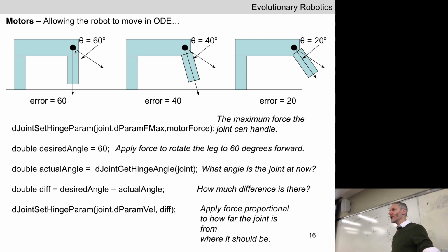Remember that a motor, for our purposes, is always going to be attached to a joint, and the motor is going to send a value to that joint. It's the torque, the rotational force that should be applied, and forces act on links. So the joint is going to take that number, that torque, and send it to the pair of links that joint connects.